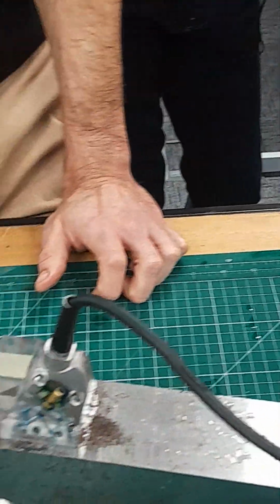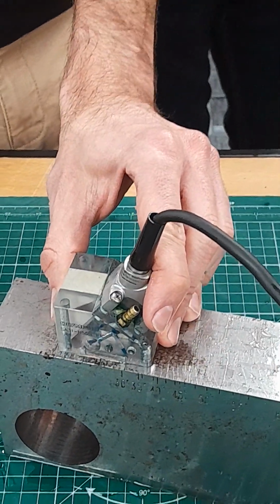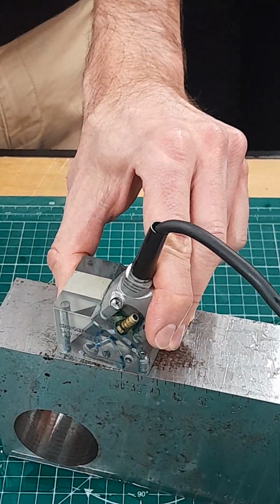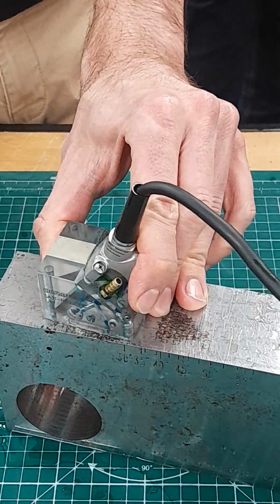So when you go and scan and you find a defect that has 80% amplitude, then you say, okay, this is comparable to a 2 millimeter hole in size, for example. Sizing wise, you would see if you measured.